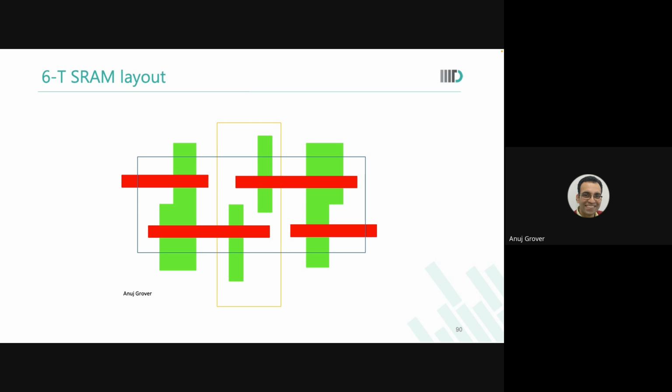And VT of the pull down being 3 sigma slow. What is this sigma? What are you playing this with? What is this sigma? Standard deviation. Sigma standard deviation, okay, we connected it from math, but sigma of what? SNM. Why would I apply the sigma of SNM on the device? This is the nominal VT that I'd want to have for my pass gate.